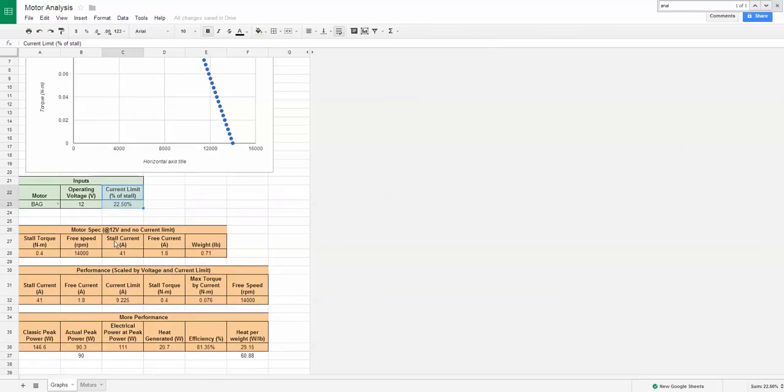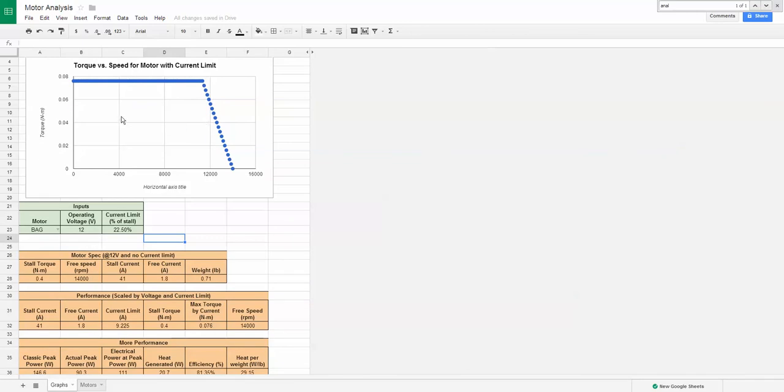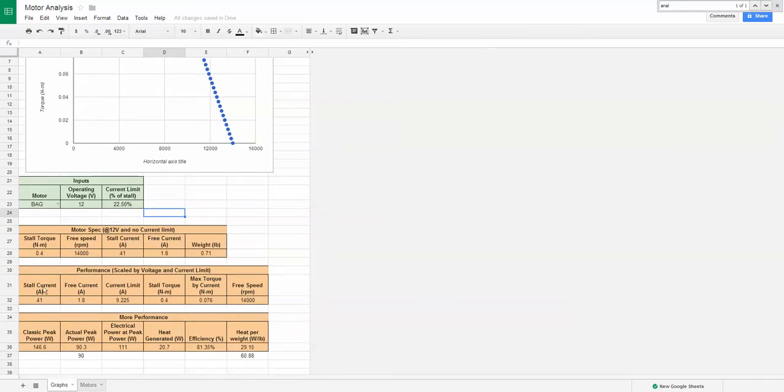And also, what is by spec a more powerful motor might not always be the best answer for your system. Certainly anything that's operating for really brief amounts of time, or pretty much always operating near free speed or peak efficiency, the higher power motor could be a better option. But for things where you might be experiencing failure due to higher load and more sustained stall, the lower power motor, and/or the more efficient motor, I guess, and/or the motor with more mass and better ability to dissipate heat could be the better option. I'm pretty confident in the statement I'm making that certainly near stall, if someone were to dyno this, and even kind of away from stall but not near free speed, the bag motor is going to whoop the 550 in most cases, even though spec-wise the bag motor is way weaker.